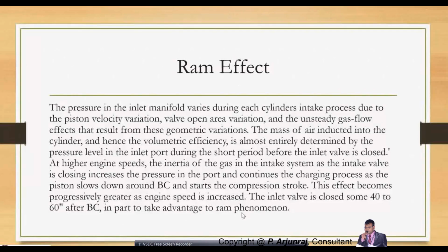You take the advantage to go for the RAM phenomena, the RAM effect, where you are also going to determine the amount of variation with respect to the other parameters, considering the inertia, speed, pressure, and also the overall system configuration with respect to the combustion parameter. Here the RAM effect is not only for the combustion, but as we deal with volumetric efficiency, basically we are going to deal only with the inlet system.